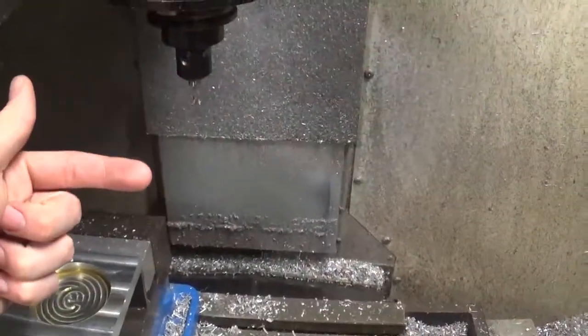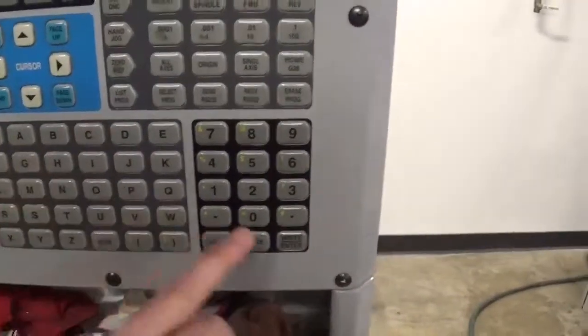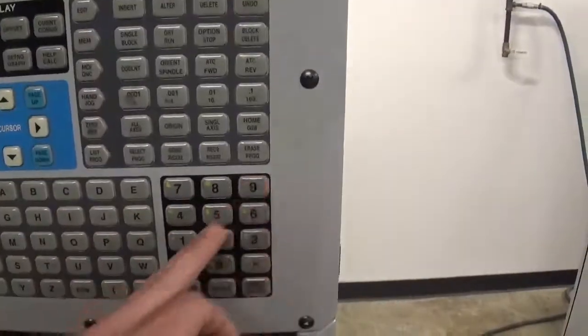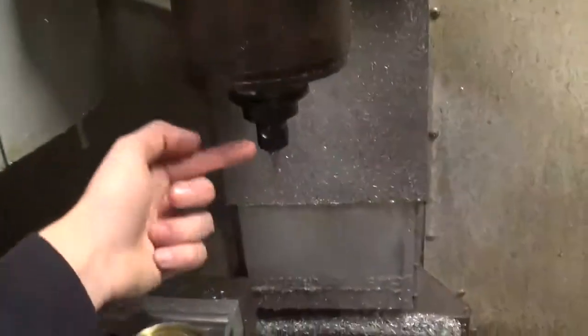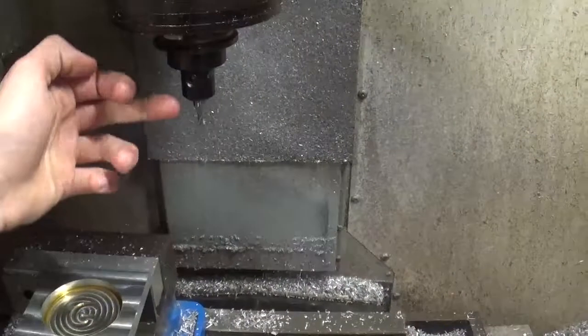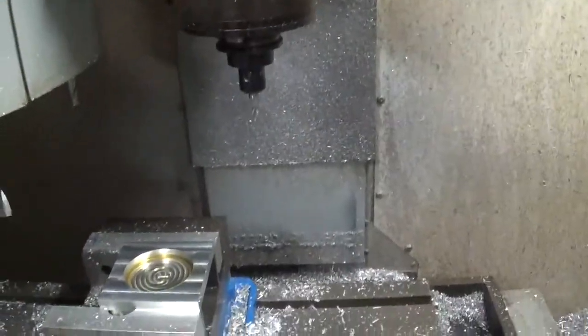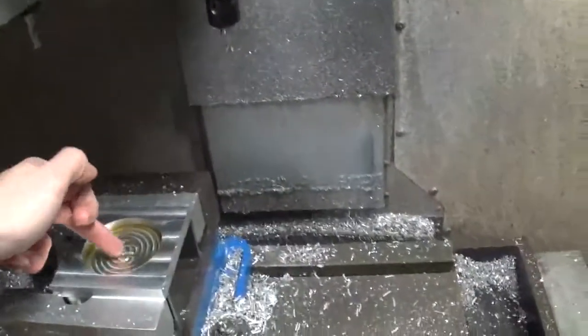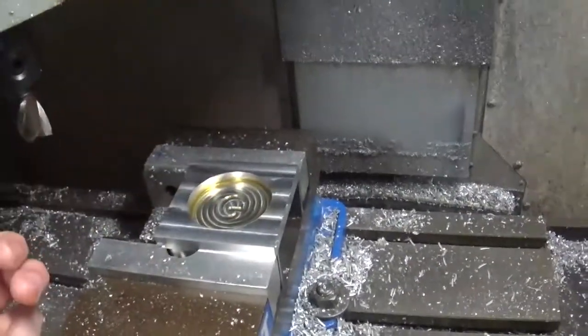Alright, now let's say I just want to move my tool from here to here. Say that's 3 inches. You can go ahead and do that in MDI as well. So I'm going to go here, make sure I'm in my MDI. I'm going to type in G00. I'm going to go G91. I want to move incrementally, so that way I'm only moving my tool 3 inches this way, because if I just type in Y of -3, it's going to pick up my work offset, which is right here currently, and move -3 that way.